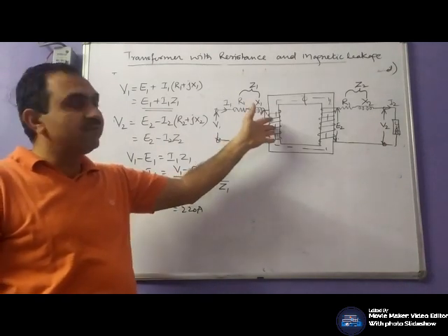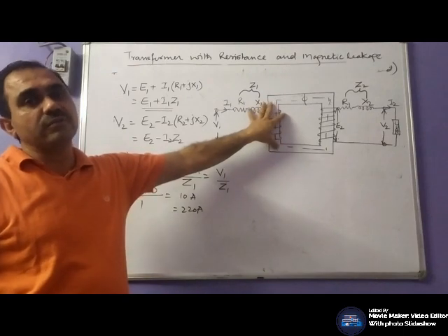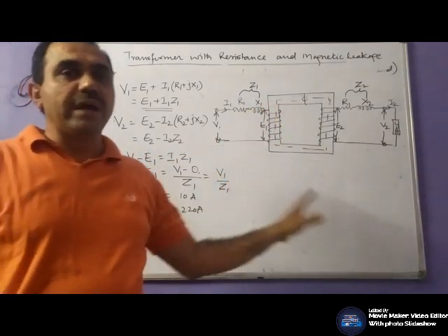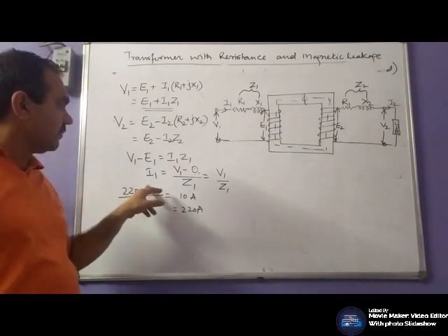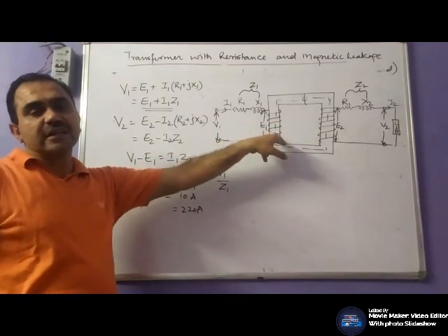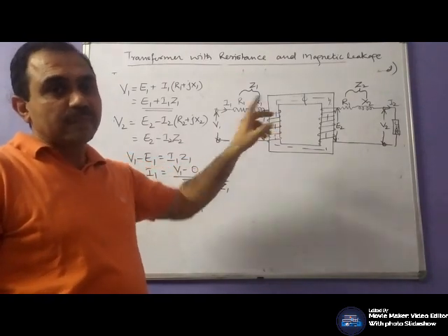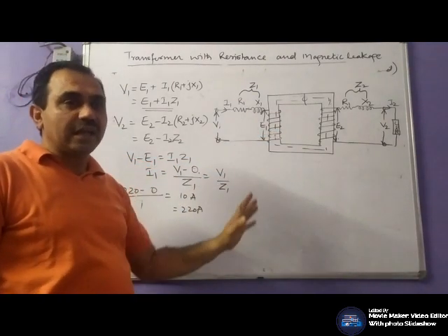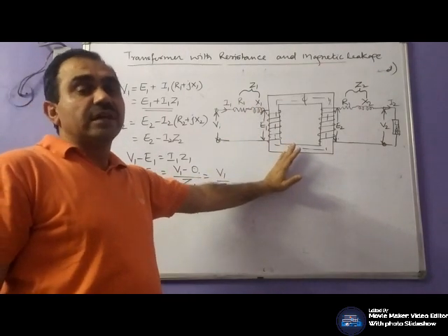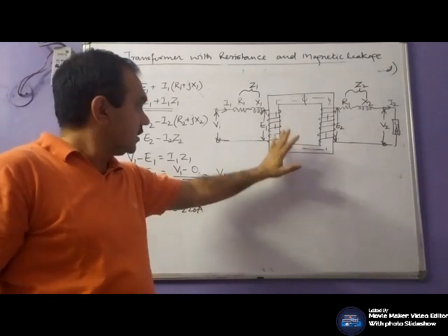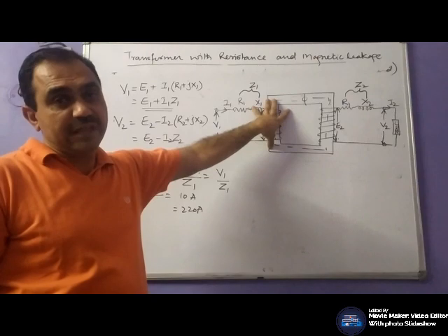Its insulation will fail and the winding will burn out. The primary of the transformer would burn out due to heavy current. As there is no back EMF, this causes a large current in the primary winding and the primary of the transformer would be damaged. When you apply DC, the transformer doesn't work, and in addition, its primary winding would be damaged.